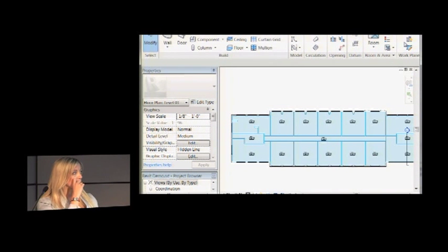Another thing that's interesting from that is you'll see Autodesk has a new tool called Vasari. This tool is a much more simplified type of model specifically for energy analysis, and that can come out also as a gbXML. So you can take the shell of a Vasari model. If you have a construction document model that's just not going to come out, you can pick your external walls and use that. But just in showing that they have developed that tool, they also understand that the complexity of a construction drawing model is often just too heavy for analysis.